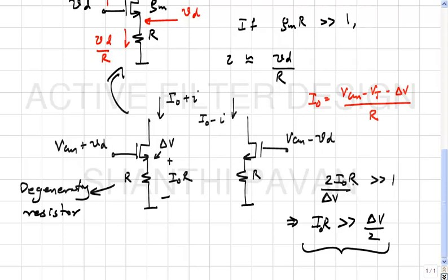Yeah, so in all the discussions that follow, I am only going to discuss the basic V to I converter. The loads will be current sources, cascoded if necessary. But the important thing to note is that there is some kind of common mode feedback arrangement which tweaks the load currents to always be equal to the current being pulled down, so that the output common mode voltage is maintained at some VCM ref. Is this clear? All that is understood when I say this is the circuit for the V to I converter, the rest of it is all understood. Does it make sense?